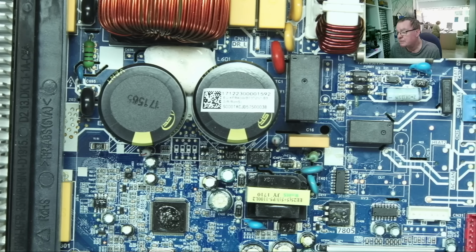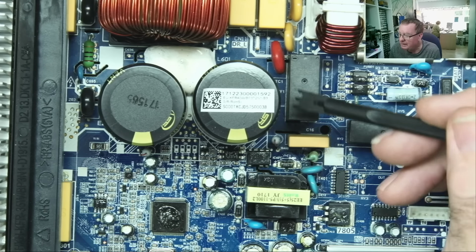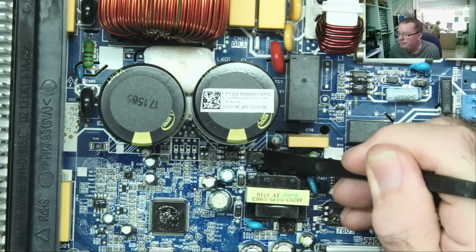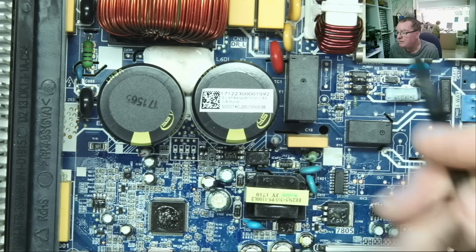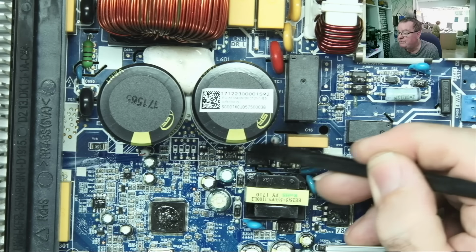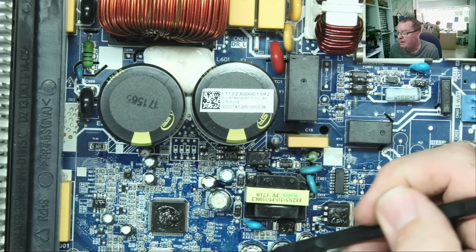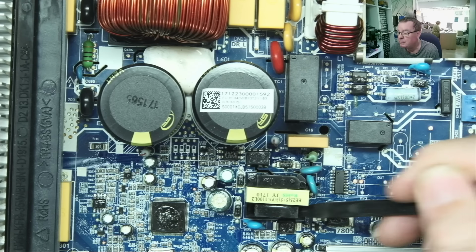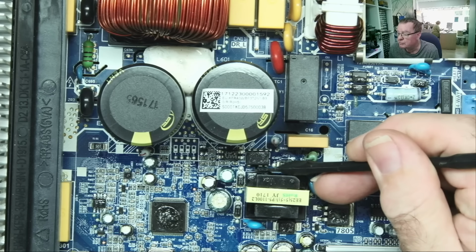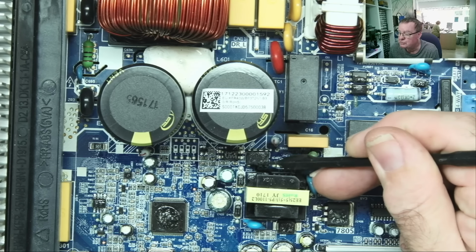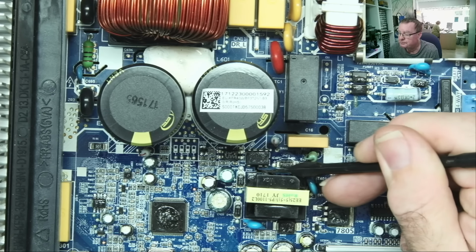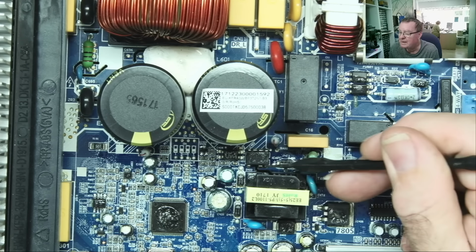And the standby supply commonly is driven by a chip like this one. This is a very common form. You can normally spot them easily. A, because you buy a small transformer, and B, because often there's a leg missing just there. That divides the high voltage pin from the low voltage part of the device.